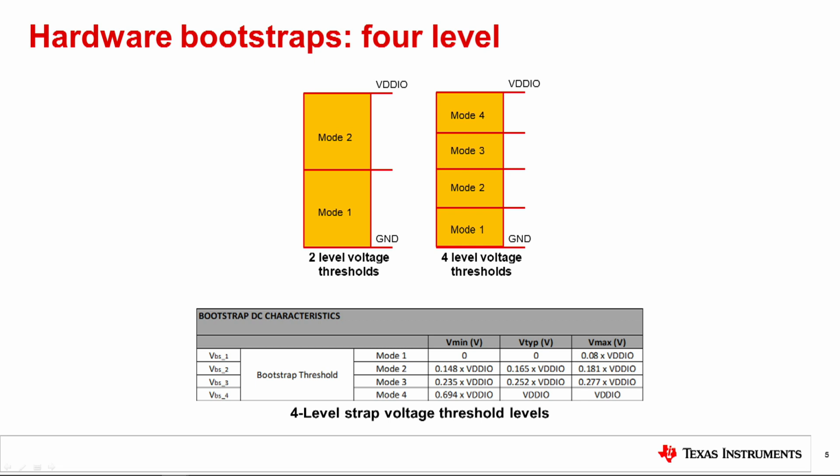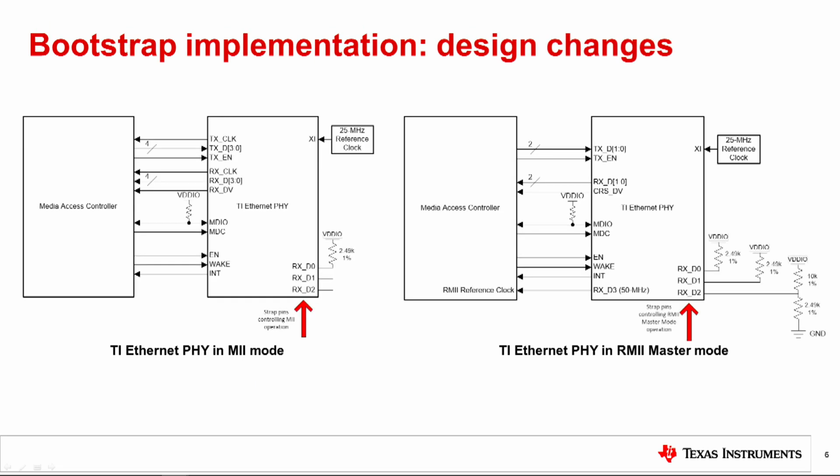Remember that strap voltage is sampled on power-up and reset. As a sanity check, you can measure the strap voltage while holding the device in reset to confirm the PHY will be set in the desired operating mode.